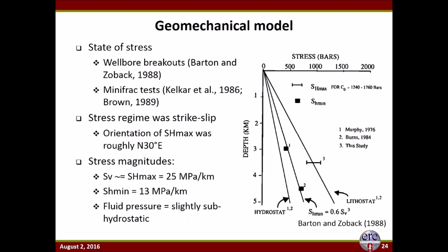field project. And it's important to understand how we arrived at our mixed mechanism conceptual model, so I just want to walk through, in the next couple of slides, some of the data sets that we used to constrain our conceptual and numerical models. First of all, it's always important with this type of problem to frame it in the context of what we know about the state of stress. And fortunately, at Fenton Hill, there were a lot of field experiments performed to measure the state of stress. There were wellbore breakouts and mini frac tests. So we had reasonably good constraints on the stress orientations and the stress magnitudes at depth.